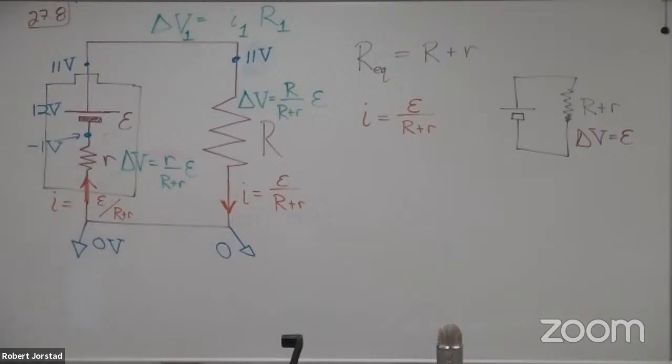So the idea here is this is a kind of a weird way to look at this circuit, but in this case, the voltage across the battery doesn't get truly displayed because you're losing some of it right here. We're losing a volt across this internal resistance. Now, this is exaggerating the thing, but remember in lab, when you had the circuit open, you got like 1.38 volts.